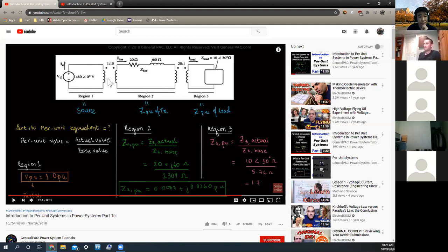So for this, it may have assumed an ideal transformer, looking at this. It may have assumed an ideal generator because the generator doesn't have a synchronous reactance. So the only thing there is a turns ratio that does voltage conversion. So then the line is the only thing you have. Or they may have reflected it already built into the line, but that's less likely. It looks like they just assumed this is the ideal transformer.